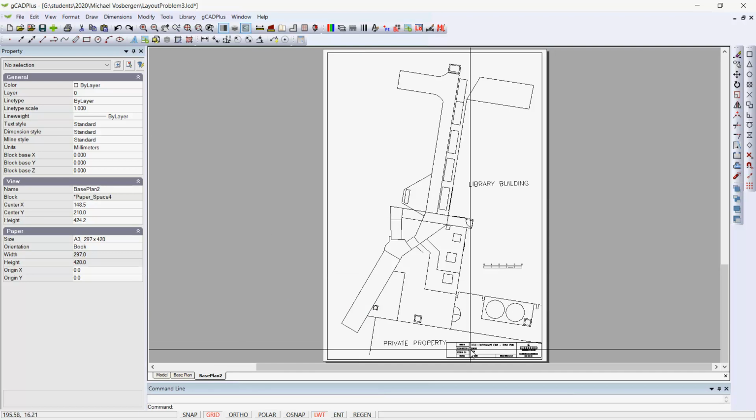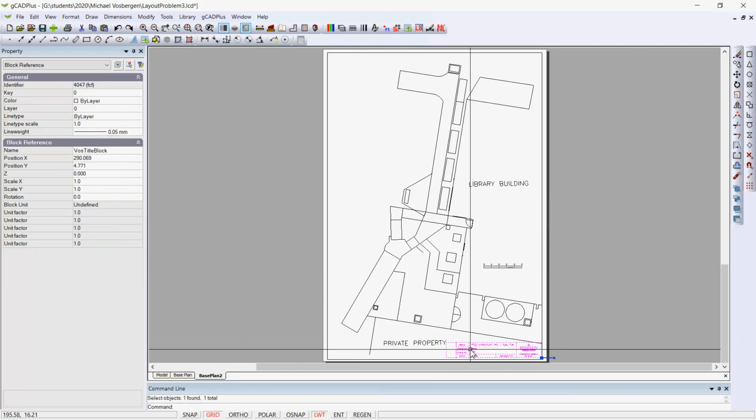So you try and use blocks by all means, but keep them simple, and don't nest one block inside the other unless you're very careful with the name of the internal block and what's in it. You clearly don't want to do as was done here, repeating information